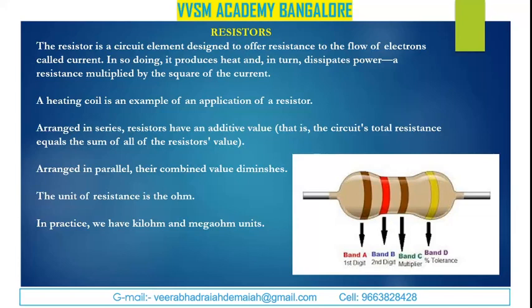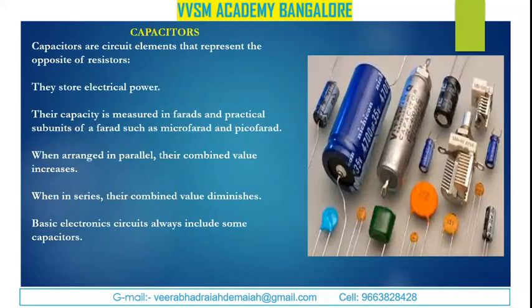The unit of resistance is the ohm. In practice, we have kilo ohm and mega ohm units. This is a resistor which indicates the color bands: band A, first digit; band B, second digit; band C, multiplier; and band D, percentage tolerance.